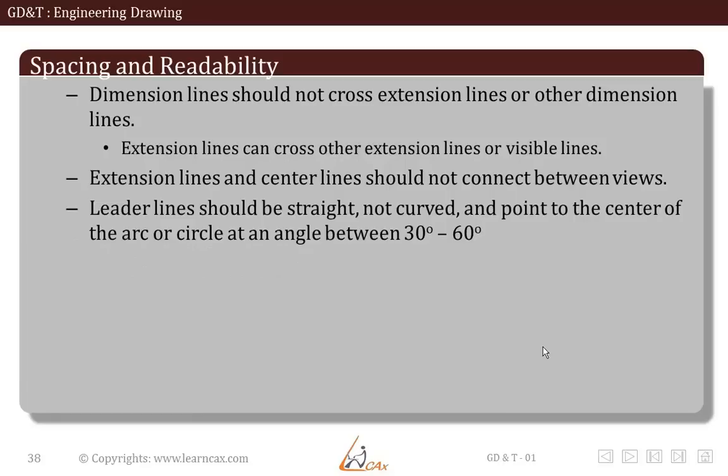Leader lines should be straight, not curved, and point to the center of the arc or circle at an angle between 30 degrees to 60 degrees. So this is something to be noted down precisely: 30 degrees to 60 degrees.